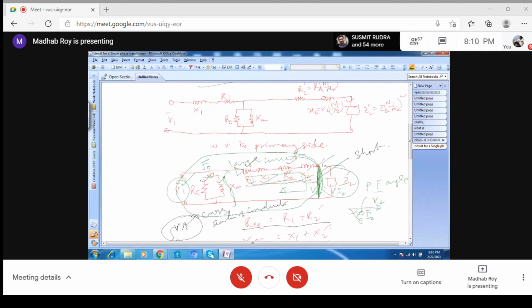Actually, distribution transformer is always used at the end. Okay, there is no further transformer beyond the distribution transformer. Distribution transformer is normally used near your distribution point. Suppose you are using electricity in your room, that is coming from a distribution transformer. Some industry is also using higher voltage, suppose 3.3 kilovolt for some machines, etc. That is also coming from a distribution transformer.